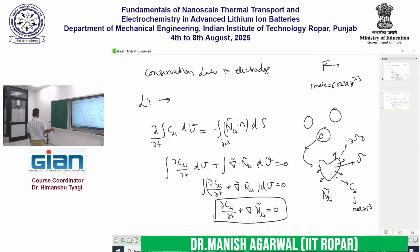Just to connect with other things, you know the heat transfer equation. In heat transfer also, if you have a domain, the heat flowing out is q dot n. The heat that is changing inside is rho Cp del T over del t, assuming rho and Cp are constant with respect to time.